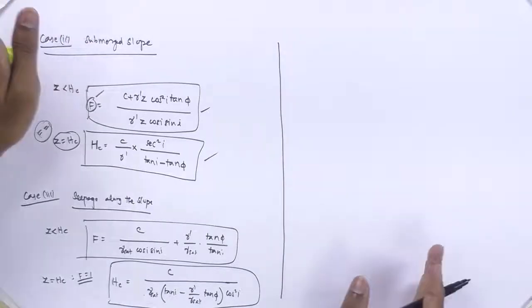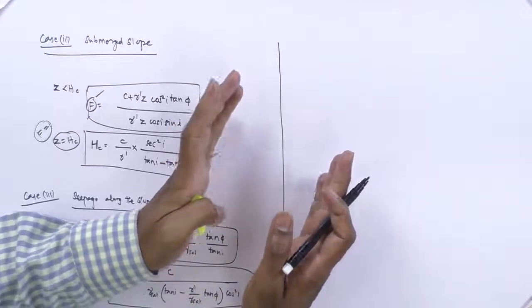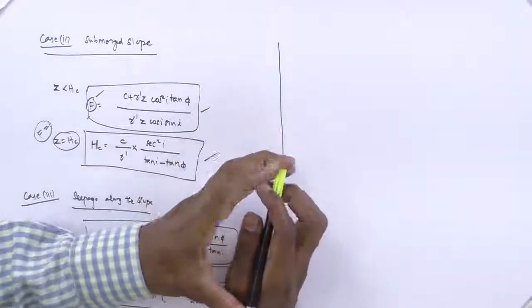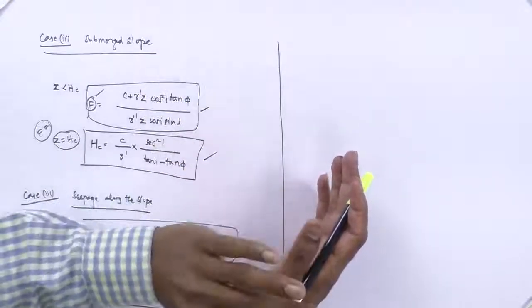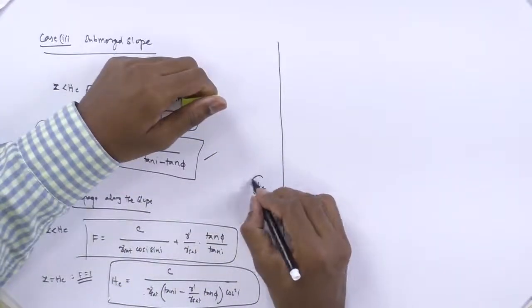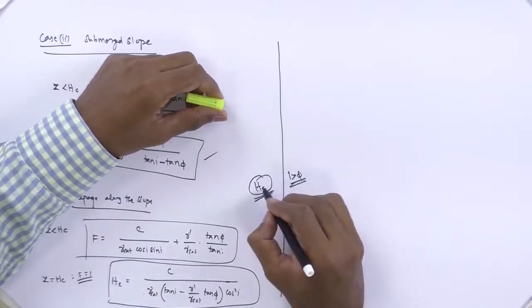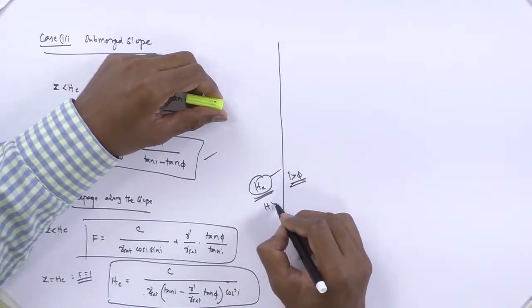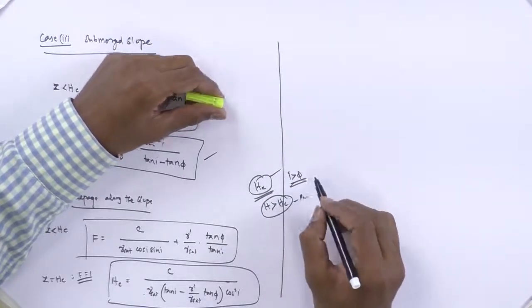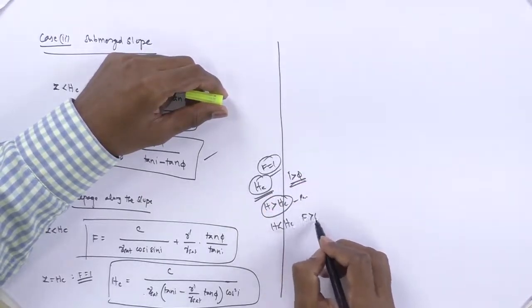I hope you have understood this infinite slope analysis for phi soil and c-phi soil. In phi soil, you cannot take the slope angle beyond phi, whereas in c-phi soil, cohesion helps to go beyond the phi angle, but it is limited up to the critical height called hc. So hc is a major thing; this is the limiting height. So i can be greater than phi, but only up to this hc height. When h goes beyond hc, it is not a possible slope; it fails. At hc, the factor of safety equals 1. When h is below hc, the factor of safety is greater than 1. I hope you have understood my infinite slope analysis on phi soil and c-phi soil. Thank you.